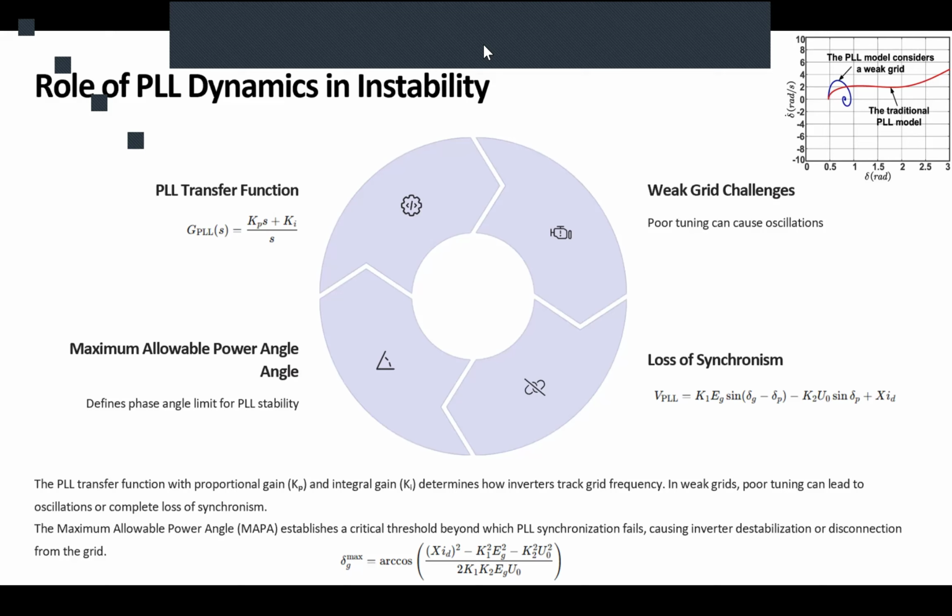So there is not going to be any damping in our system because the grid itself, the reference itself, is varying, and we define our PI controller to work in stable scenarios to reduce the error. Now, not only does it try to reduce the error and fail, but also the variation in reference adds up to that failure. So we are going to end up with an oscillation.